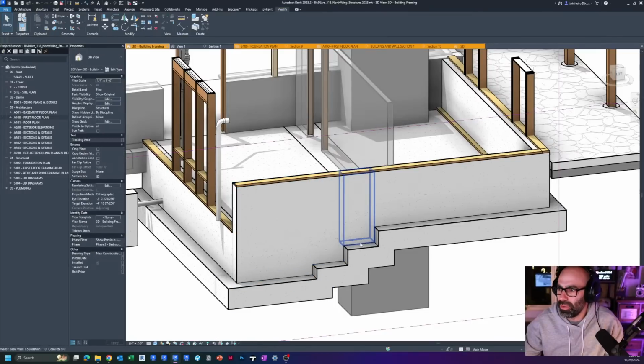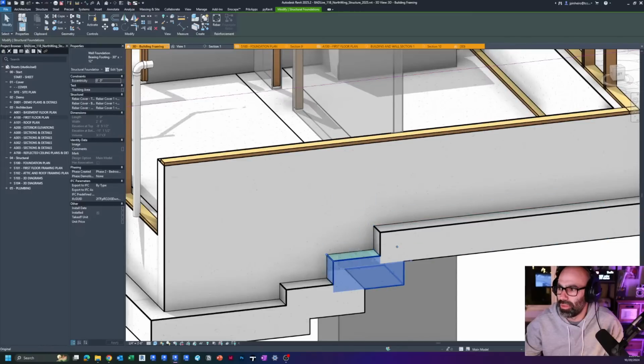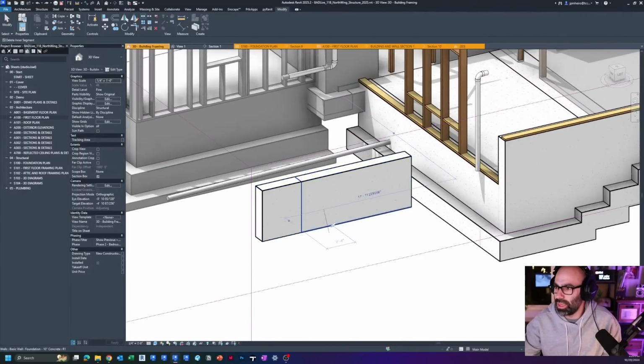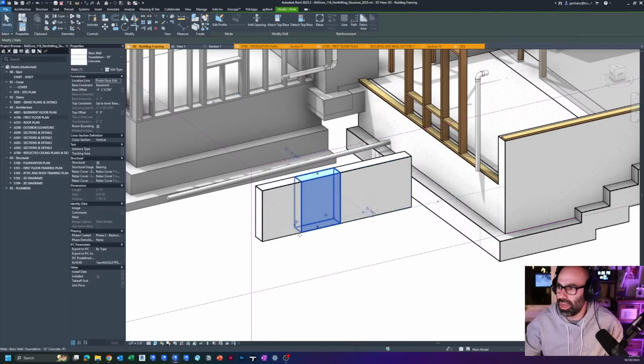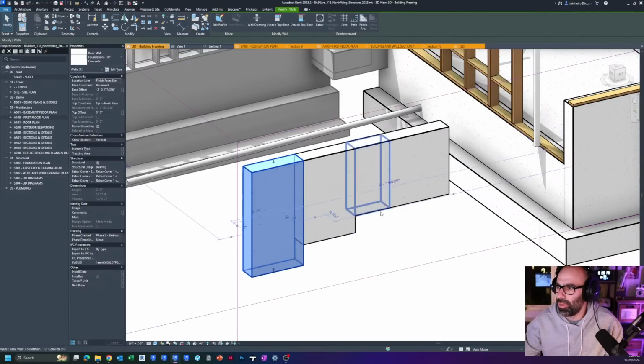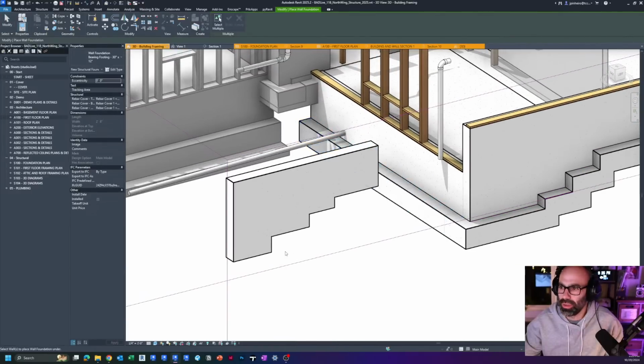I just have 4 different walls, and then I have a strip footing, and then I change the offset of the footing, right? So the way you create this is, again, I'll split. So not split between. Try that again. We'll do a split. Don't delete the intersection. So SL for split. And I'm just going to split this a couple places, right? So now I have 3 wall pieces, and whether you have levels or not doesn't really matter. Let's just do this. And then I'm just using a strip footing. So create similar, place it here, here, here, and here.